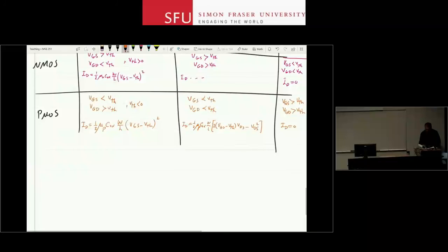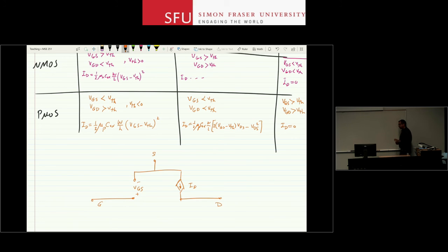The model you use for a PMOSFET is like this. Well, okay, it's actually upside down normally. So this is ID, and this is VGS, and then ID is from one of those equations in the above. You can use the same model for an N-MOSFET as well, but if you've done enough problems with BJTs, you probably can go past this model and start using equations directly on the circuit diagram.